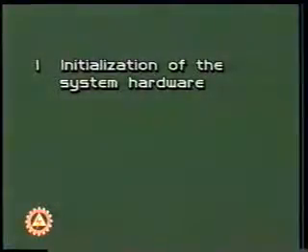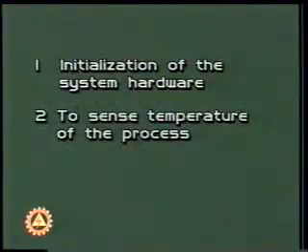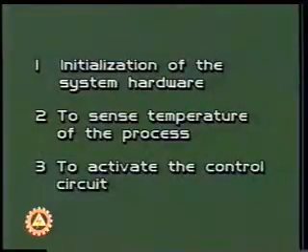On completion of circuit design, our next step is to convert the desired operations of the system into detailed flowcharts. We follow a modular approach, and for this purpose we divide the complete system functions into 3 steps. Step 1, initialization of the system hardware. Step 2, sense the temperature of the process, and step 3, activate the control circuit.